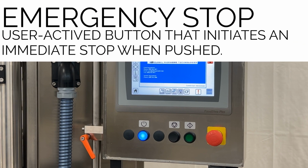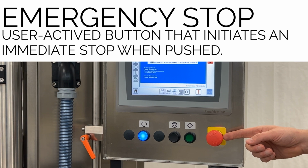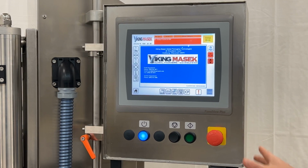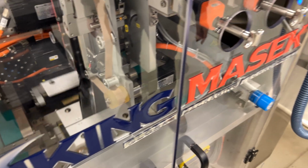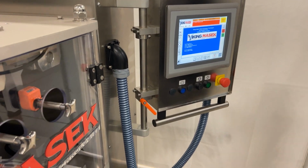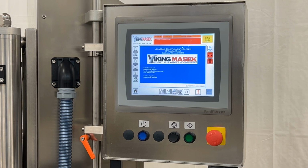Emergency stop. The emergency stop is a user-activated button that initiates an immediate stop when pushed. An emergency stop turns all motor drives to a safe state and releases air pressure from the pneumatic system. The emergency stop causes an immediate and jarring stop to machine functions. Only use this button in emergencies because unnecessary e-stop usage causes premature equipment wear.